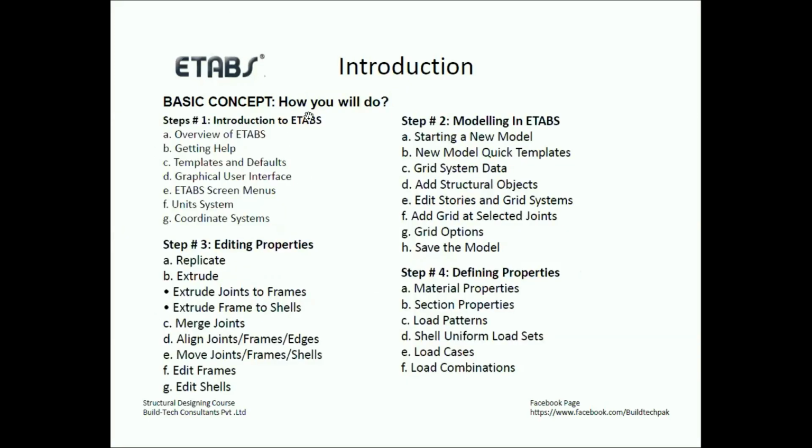Coming towards further activities, if we look at the ETABS overview I gave you at the start: templates and defaults. I will show you in ETABS that there are templates. Instead of modeling from scratch, if you do not want to model the building completely from scratch, you just select one of the templates, like I want to design a flat plate slab system. Instead of starting from modeling columns and beams and everything, there is a template there, just select it. It will automatically form beams, columns, and everything. I will show you some templates. The graphical user interface we will also see in the next session.